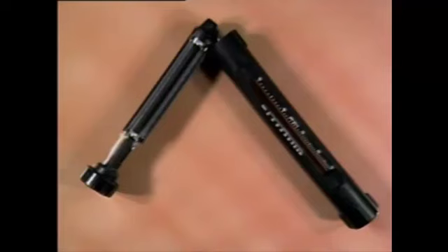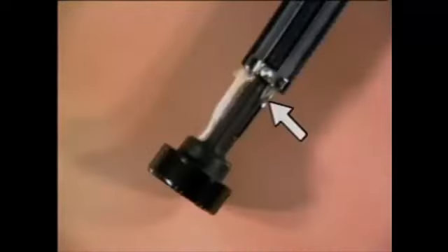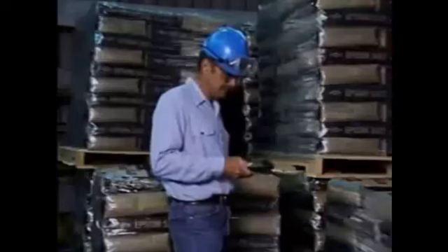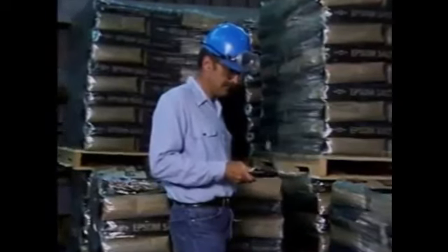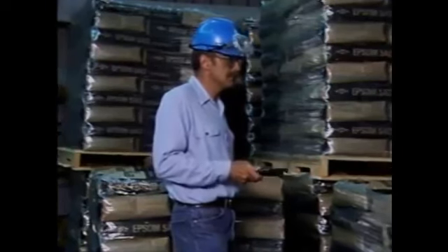This particular sling psychrometer consists of two thermometers that are mounted on a frame with a handle on one end. One thermometer is called a dry bulb, and the other one is called a wet bulb. The wet bulb is partially covered by a wick soaked with water. To obtain a humidity measurement, the psychrometer is slung through the air for about 20 seconds.